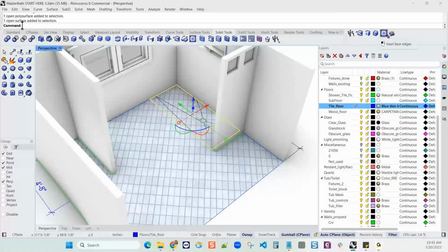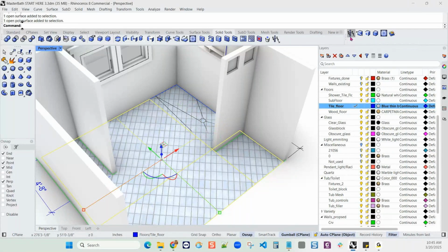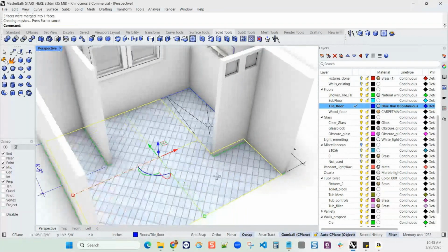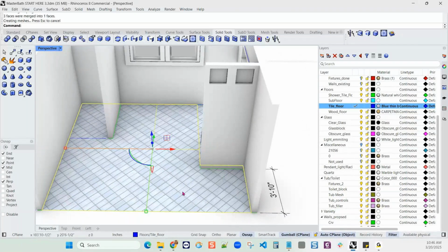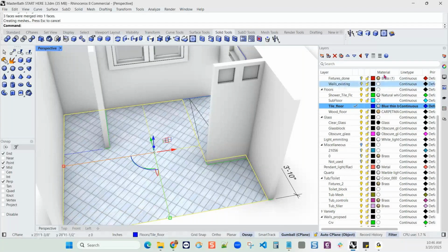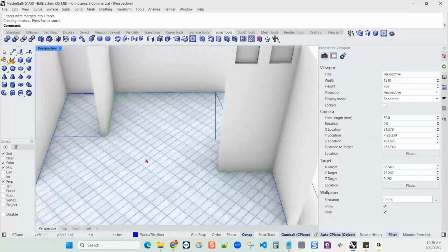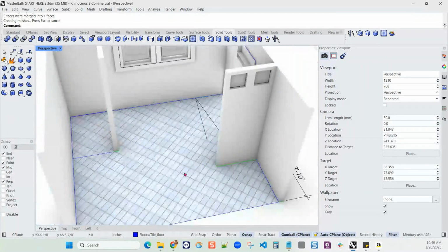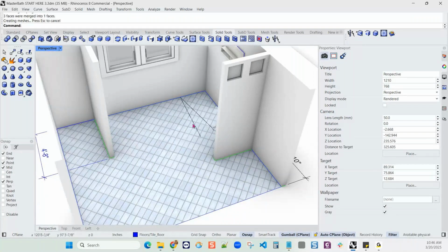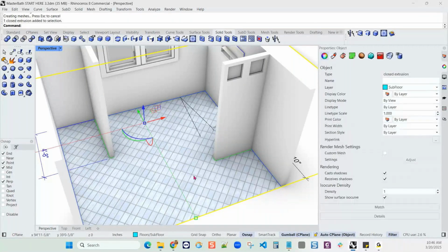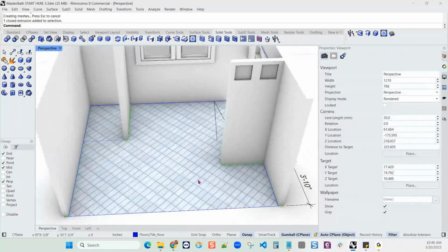There's merge all coplanar faces. So I can pick this poly surface and merge all coplanar faces. And that way it now has lost those division marks. And if I look at it here, it is just one trimmed surface. And it's only aesthetic. It really doesn't matter in the behavior of it, whether it's a surface or a poly surface. Join has to join on edges. So if I would have grouped it together, it wouldn't have made sense because it's already selecting as one object.